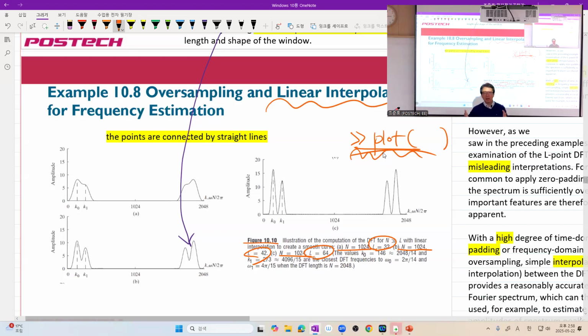So your DFT output does not reflect any effect outside your window. So you actually distort the signal a lot by cutting out most of the information except within the window length. And then you replace the original signal with a time-limited signal, and then you sample, and then you perform the DTFT, and then you sample the DTFT by doing the DFT. Got it?